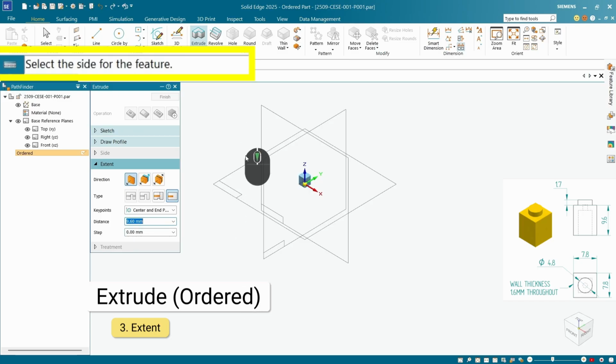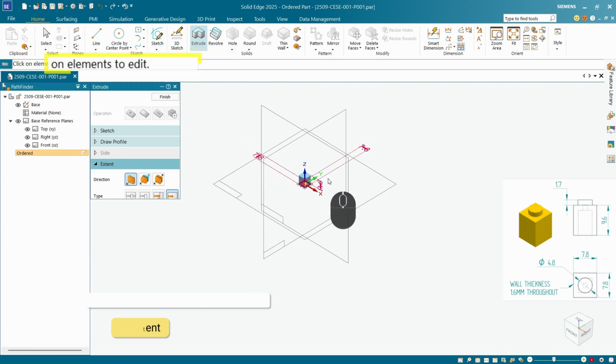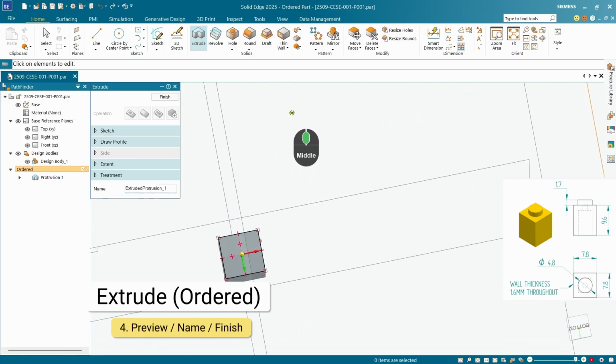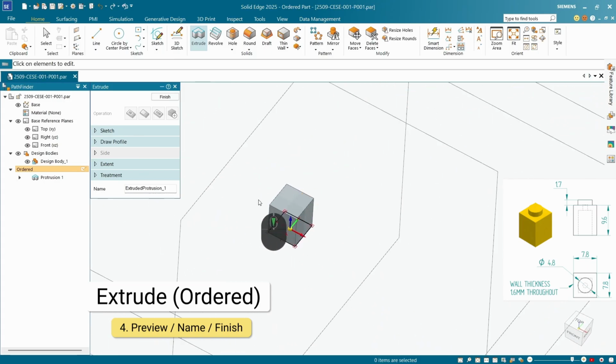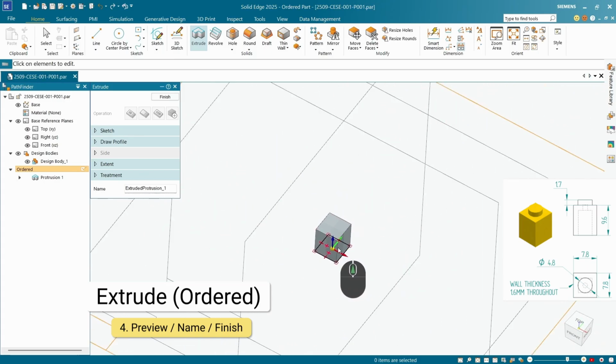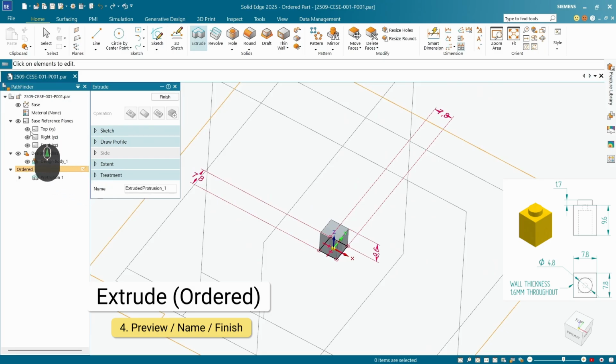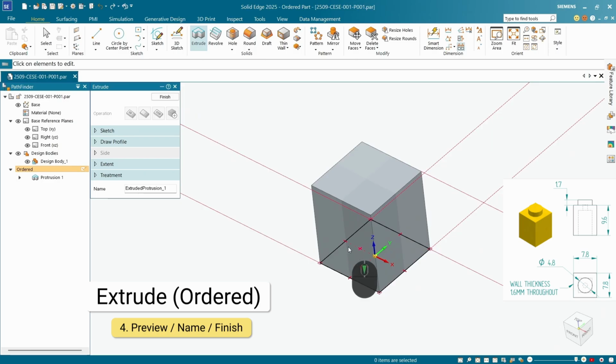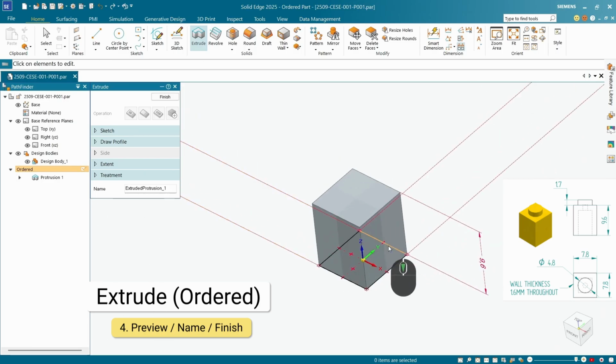Now it's actually waiting for which side of the part, so we can go down from the top plane or up. I'm just going to choose up. Both ways are okay. And that is the basic part. You can see a little bit of differences in color there. That's actually where the different reference planes intersect the part. So if you're thinking there's something missing, you can see a kind of a darker grey area and lighter grey areas. That's because there's a plane coming in here and a plane coming in here, and everything's a little bit lighter behind the planes. So I can just turn off that display, and now the whole part looks uniform.